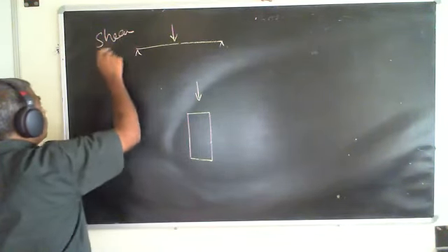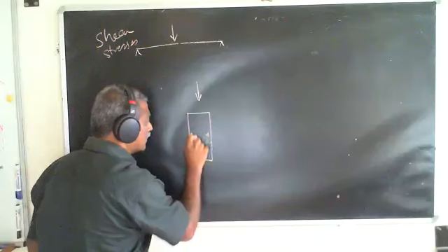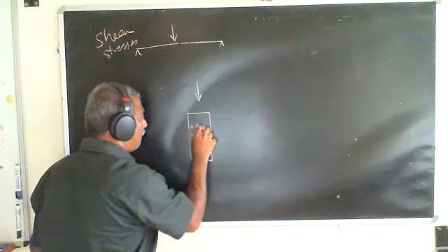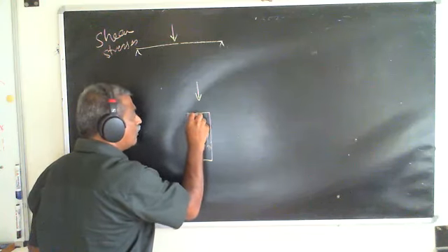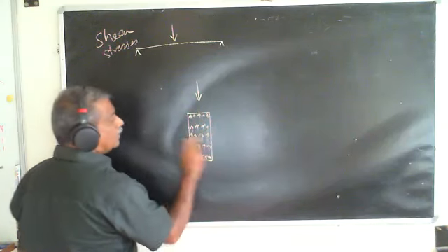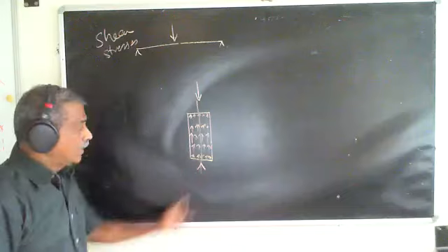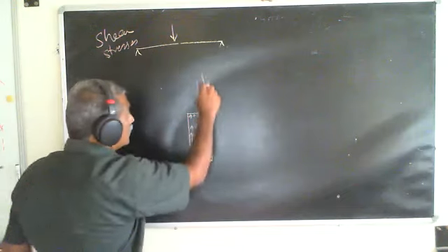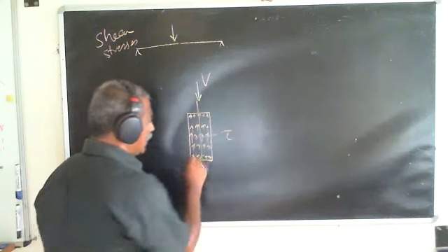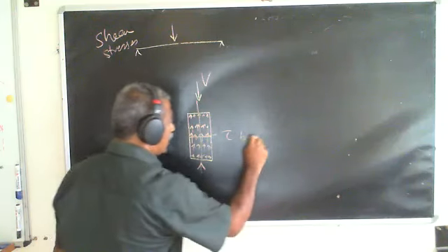Okay. How will the shear stresses look like? They look like this, right? It will taper off to a small value as it goes to the end here. Similarly here, the value is higher here, but the flow seems to be going from here to here like this. Okay. And this flow is opposing this flow, this shear stress. Okay. This is tau. And if I multiply by the thickness, which is B, I'll get the flow, Q.